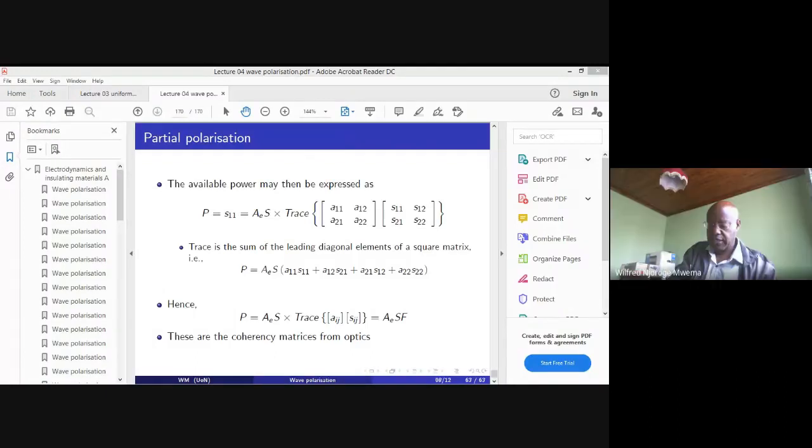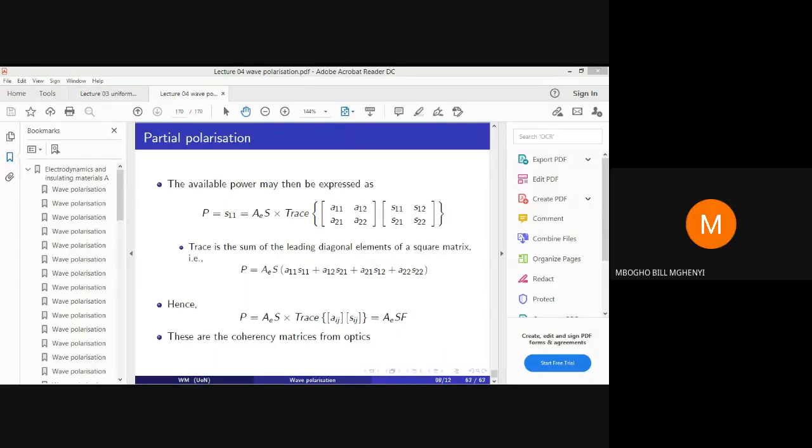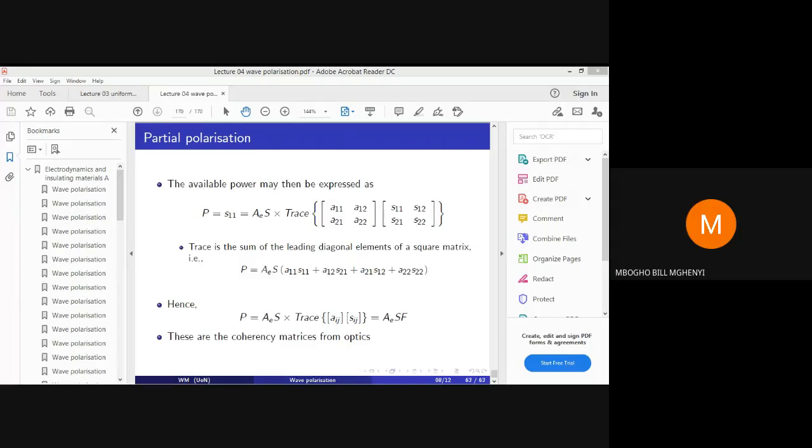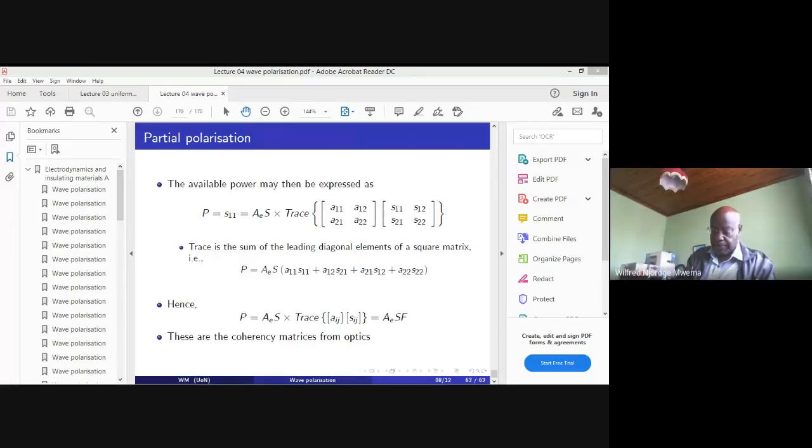The curl of H is equal to J plus d/dt of D. Now write J equal to sigma multiplied by E. Then add to it epsilon multiplied by d/dt of E, because D is equal to epsilon multiplied by E, and I'm assuming epsilon is not a time function.